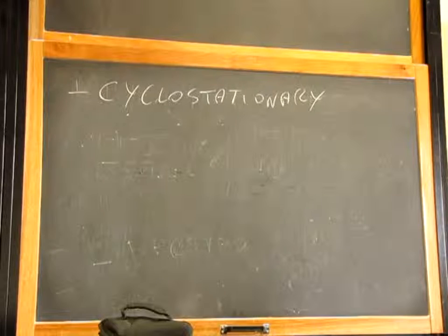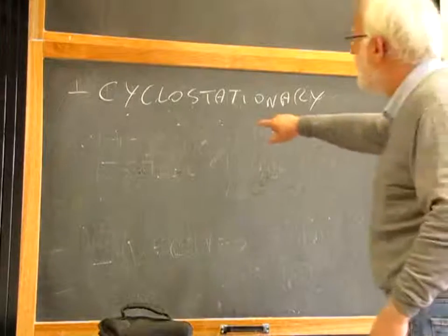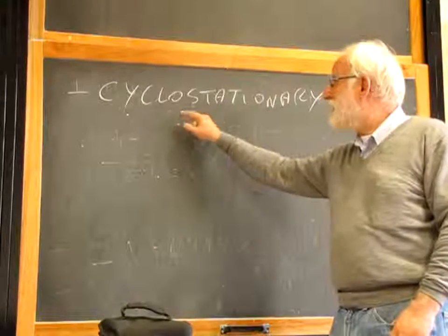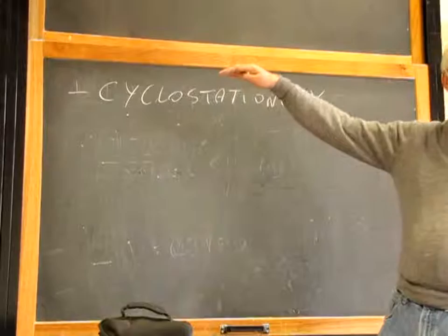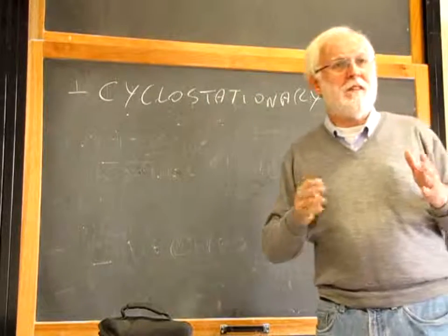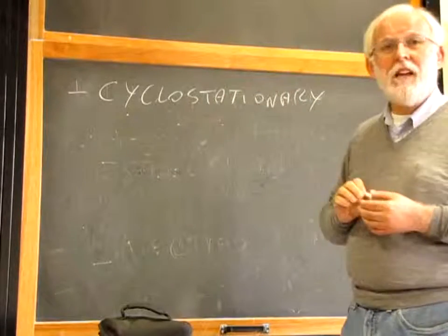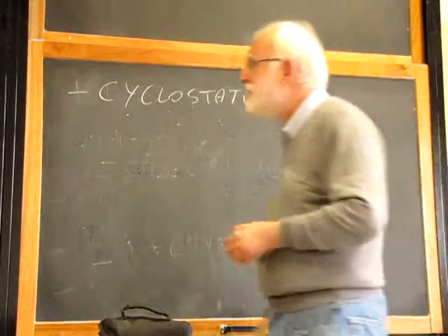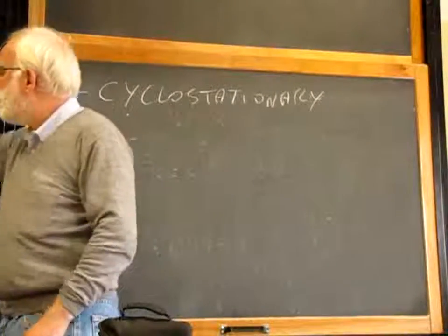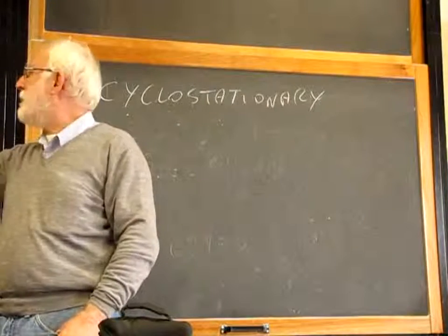It means that each cycle is equal to the previous one. All the cycles repeat exactly with the same shape, same values, etc. It is the equivalent of the DC bias point for a linear circuit. We will remove this. When we get to the small signal system, we will say, okay, it's not cyclostationary anymore. We can change the parameters and see what happens at the output. Okay? Those are our guidelines. By the end of the class, we will remove these. By the end of the class, we don't remove these.